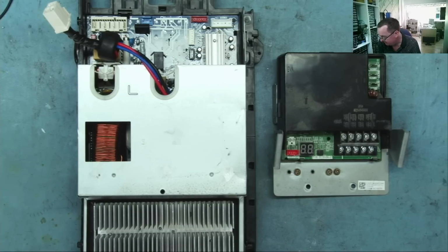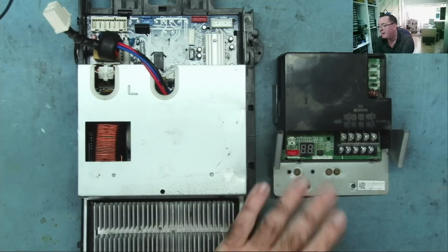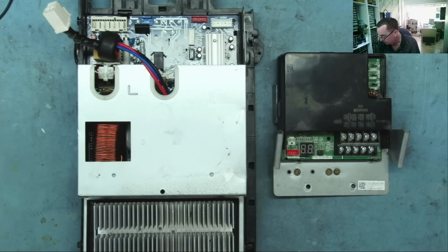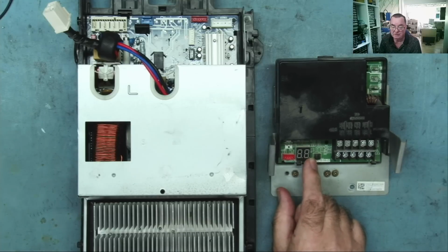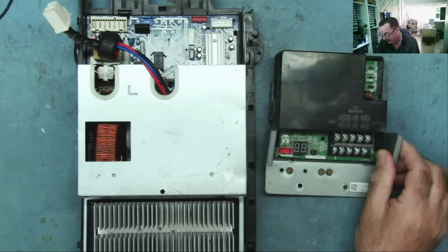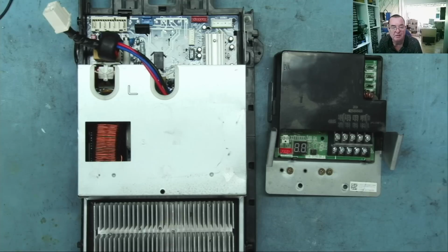So the guy has been out to this, he had a look, he says the fault is in the PCB or the controller board, and basically asked me if the guys could call me, so they called me. I went out, and this time I actually went out to the unit. I didn't see the error code because he's told me what the error code is anyway. That's fine. I did check, and I know there's mains power getting onto it. But this board, the little 7-segment LED display, doesn't light up, doesn't seem to do anything. Nothing's really happening on this unit.